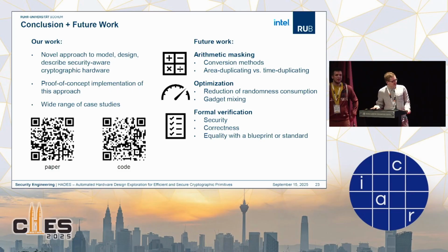No, that's exactly the point. We don't want to synthesize every possible design because that would take ages. So what we actually do is we count the amount of gadgets that we have. We count the amount of AND gadgets, the amount of XOR gadgets, the amount of registers, and we have pre-synthesized a list with the approximate size of these gadgets. Then it's basically just, if we have 100 AND gadgets at the cost of, I don't know, 200 gate equivalents, then it's 100 times 200, the area of the AND. Okay, that makes a lot more sense.